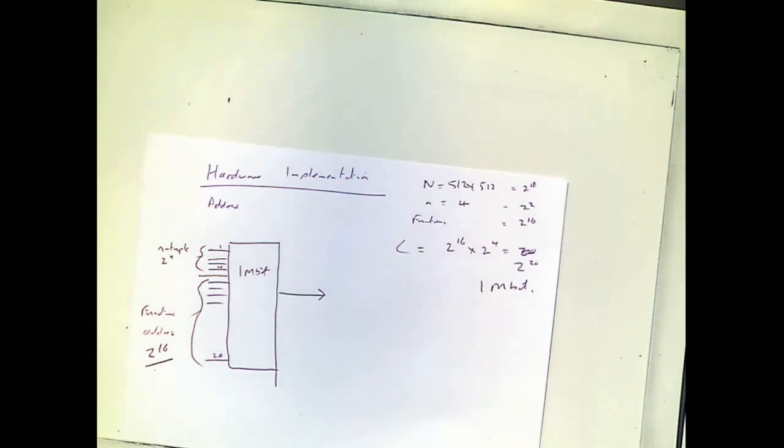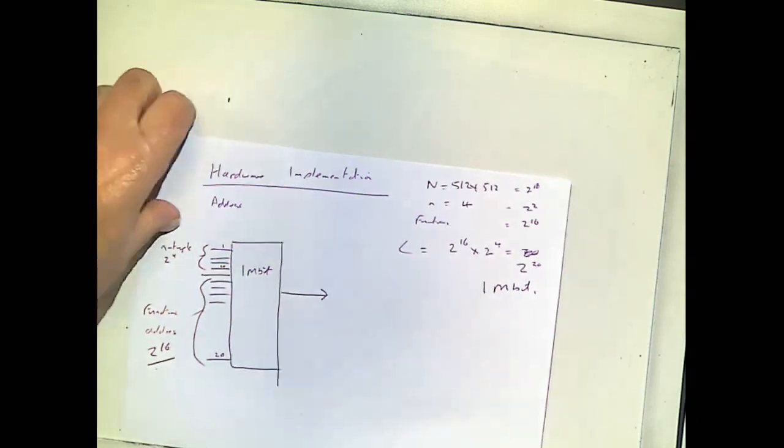65,536 accesses of that memory. And if it's working at a microsecond, it's going to be 65 milliseconds. Take the memory a little bit faster, and we're well within the time of the capture rate of an image, which is going to be milliseconds. So we can organize this system to scan through the whole of the network between capturing pictures. So we can actually implement these systems not as a parallel system, but as a serial system. So that's the concept of breaking up the memory.